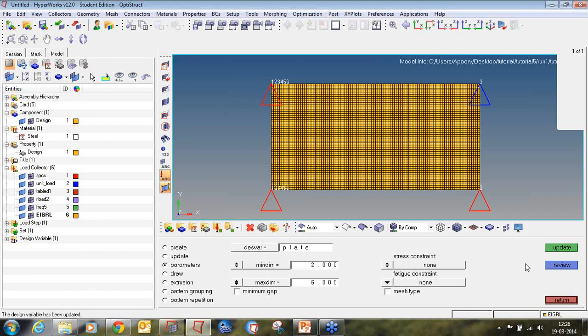The objective of this exercise is to determine where to locate ribs in the designable region. Therefore, a non-zero base thickness is defined, which is the original thickness of the shell. The maximum thickness defined by the T field on the P shell card should be the allowable depth of the ribs. Currently, the T field of the P shell is still 0.15, as you can see.